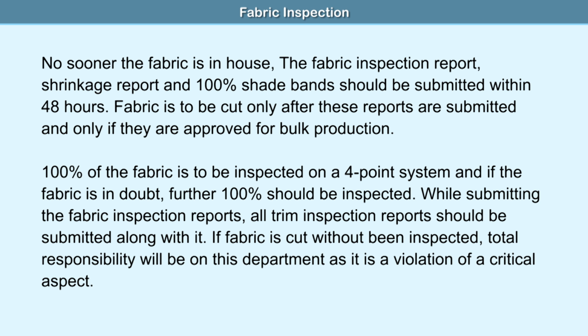100% of the fabric is to be inspected on a 4-point system, and if the fabric is in doubt, a further 100% should be inspected.